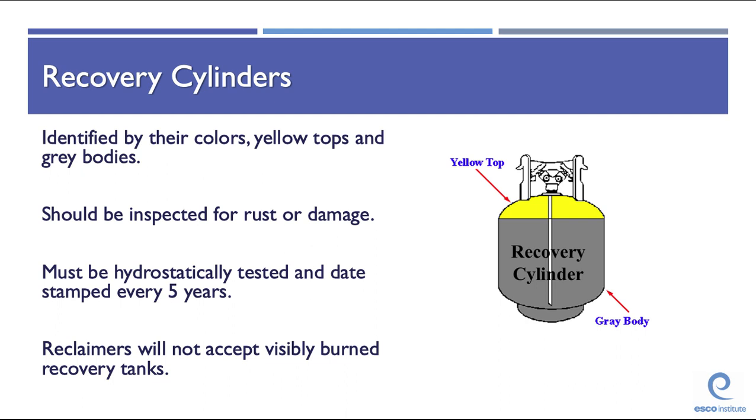Refillable cylinders must be DOT, that's Department of Transportation approved. That's important, it's on the exams. Approved refrigerant recovery cylinders can be easily identified by their colors, yellow tops and gray bodies.